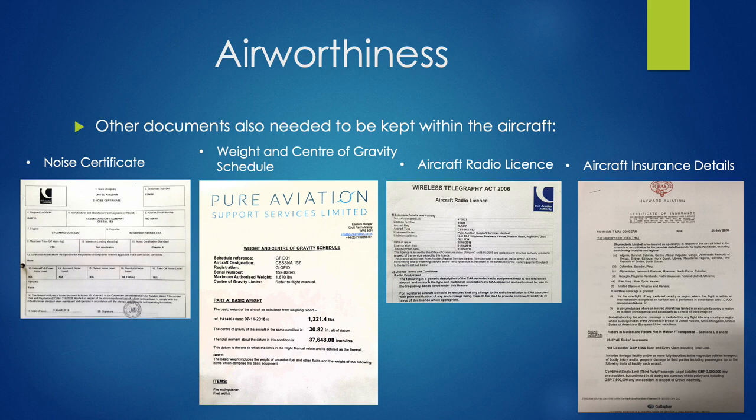As again, if we have a ramp check, so somebody comes out to the aircraft and asks to see these documents, if they're not available, then we could obviously be in trouble. So part of the pre-flight inspection in the morning will be to check that all of these documents are not only available, but also in date. Okay, they do have an expiry date, so making sure they're all valid before we go flying.